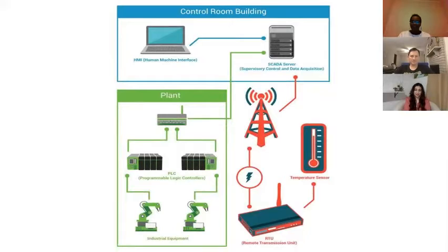This is an outline of your traditional SCADA system. The PLCs and RTUs communicate with the facility machinery and devices and send information to the human-machine interface controlled by a human operator. The operator monitors and controls the system and sends the data to the SCADA server, which then sends commands to the process. This process can be done on-site or remotely.